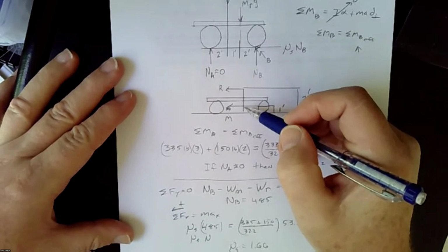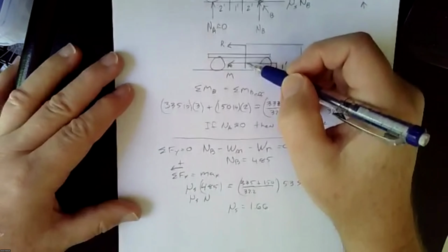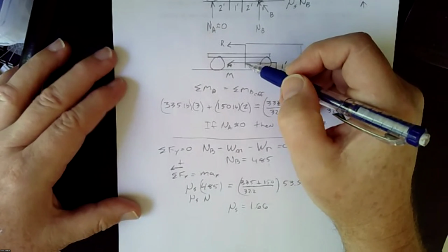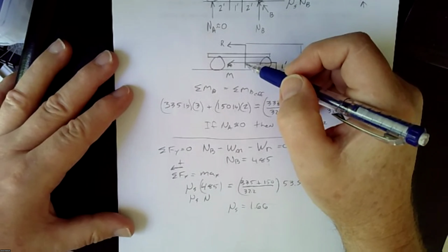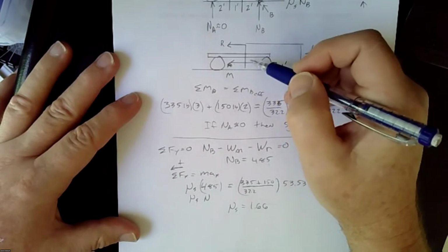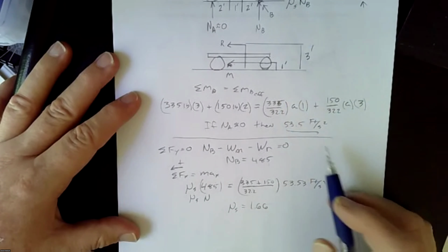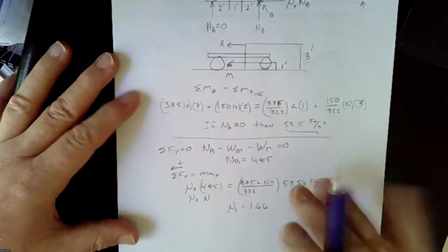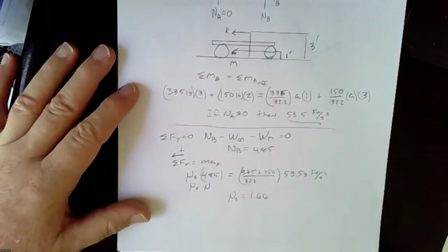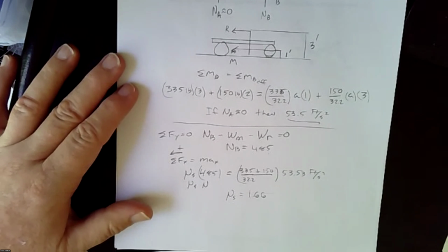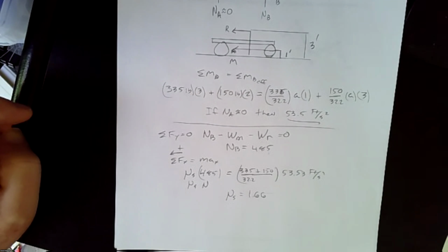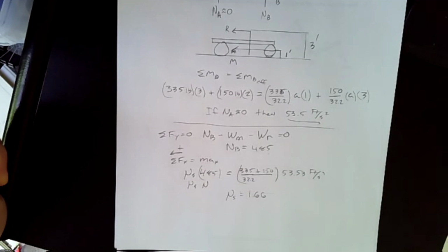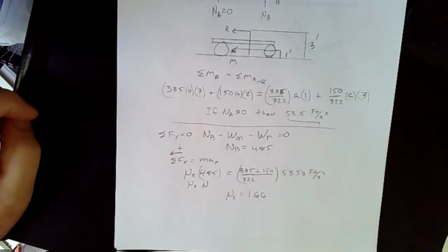So basically, I don't know how that's even physically possible, but even if they crouched to 1 foot, then the coefficient of friction, I'm sorry, the acceleration that it could handle would be 62.1. So the question is really more of a qualitative one. It says, in order to increase acceleration, should the rider go straight up or down? Well, they obviously should go down, because that's going to lower the moment created by their center of gravity. That's the important takeaway here.